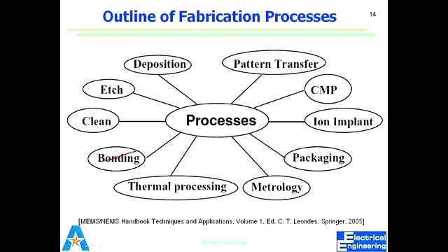Now, take the same example: even if I just have to make a resistance, I may have to do doping into the substrate for a certain length and a certain width. If I look at it from the top, I would have this region which is heavily doped. I can cover everything up and make a connection from here to here, with this region open for metal connections. So this would be a simple resistance.